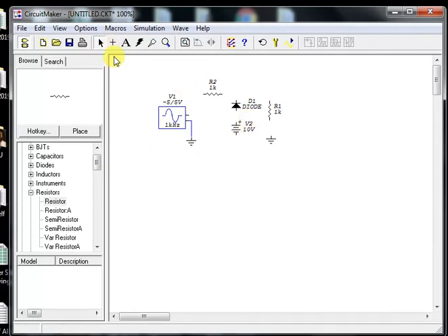Now we have to make the connection. What we'll do, just go to the plus sign, connect this resistor here, and we have to be careful. If you do not connect properly, you will not get output, so you have to be very, very careful. Now this is your output resistor. This will go to the ground, and this resistor also should go to the ground. Our connection is done, so I will click on this arrow tool, and this is how your circuit looks.